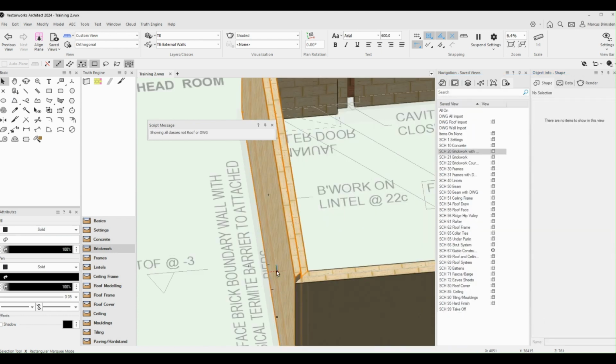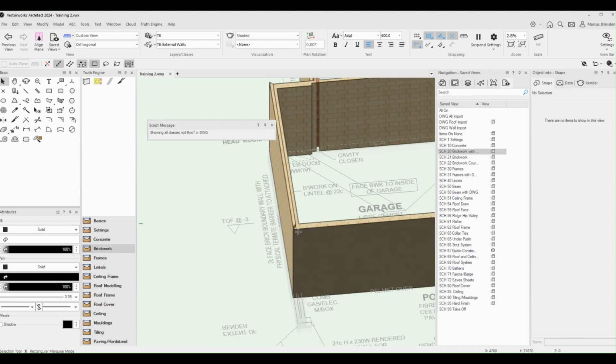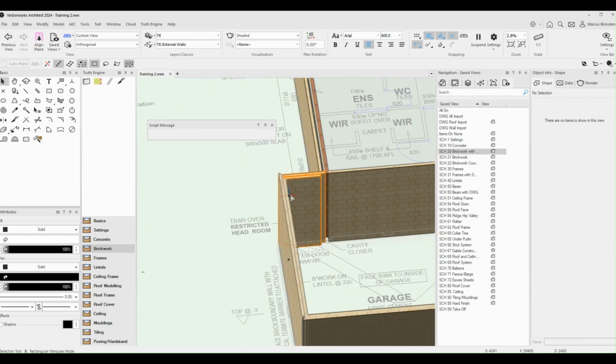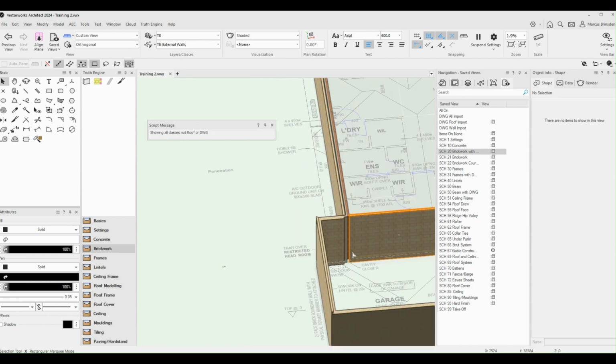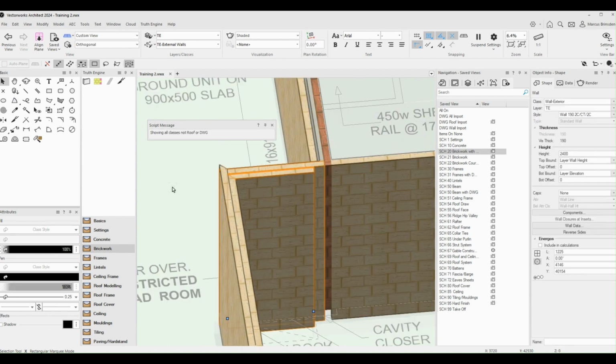There we go. And if we zoom in, you can see how the external leaf is one course higher as compared to the front and the back. We will be dropping the ceiling height down to 25 courses, but we'll go through that a bit later. And this is your stock standard two course face wall.